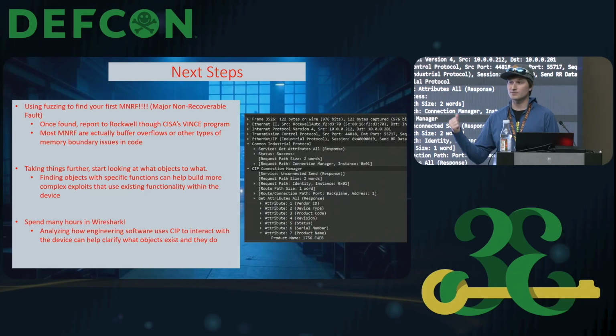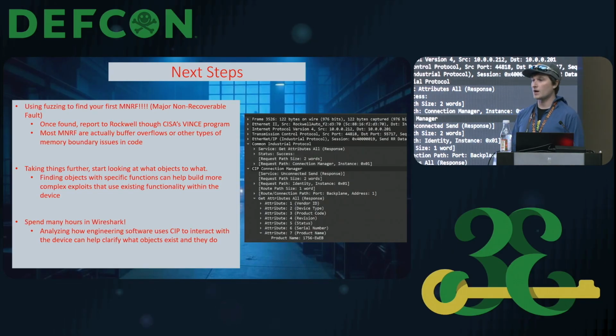Like generally these systems are fail-safe. So if one of these computers crashes, you have relay logic, and as part of the electrical installation, how these systems are wired, your valves should go to whatever their safe position is. Maybe you're venting that vessel. Maybe you're cutting off the flow of product into that vessel. But still, you have caused a disruption that very potentially could have major impacts.